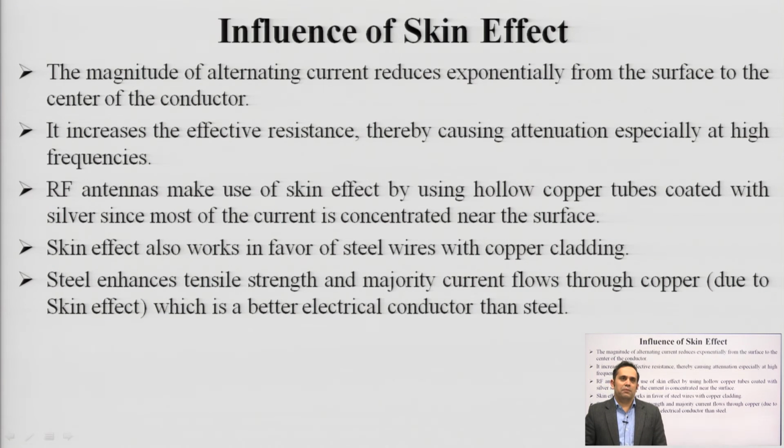No, it is true that there is a lot of concentration of current, but this is something which you can also exploit in some applications. On the negative end, it does tend to increase the effective resistance, because it is reducing the effective surface area of your conductor, because your current gets concentrated within a few microns of the surface. So, the effective surface area tends to reduce, and since resistance is inversely related to area, it tends to increase the effective resistance. So, at high frequencies it can also produce attenuation.